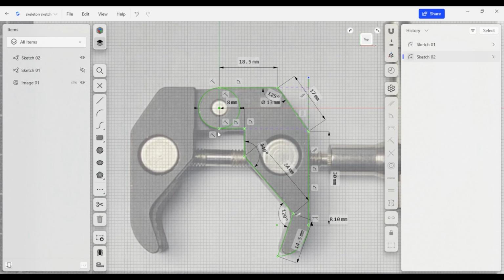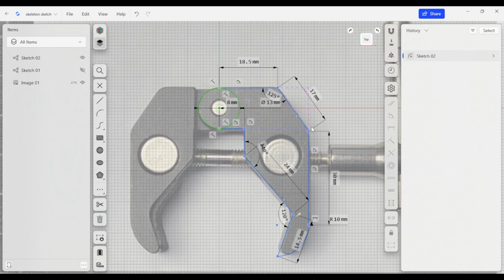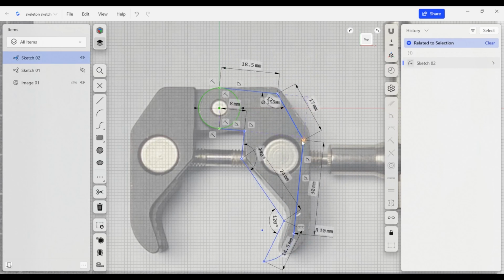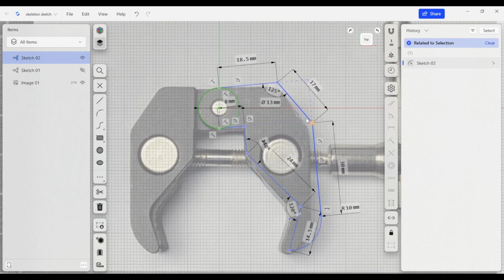And what I'd like to be able to do now is make sure that when I unlock this sketch, I will rotate around this center pivot point. So everything's keyed to this vertical line here. I'm just going to delete that line. Everything turns blue. And now I can rotate this sketch. And you can see that we're getting some constraints here that are not behaving the way we'd like to.